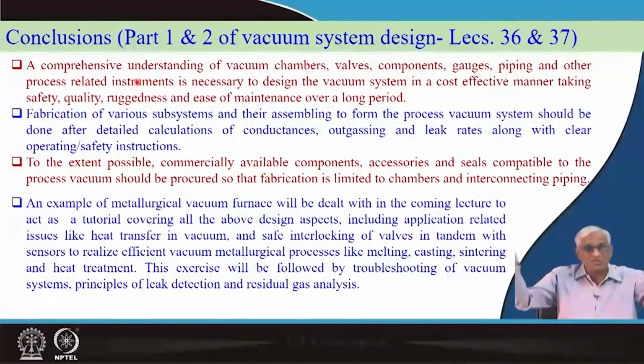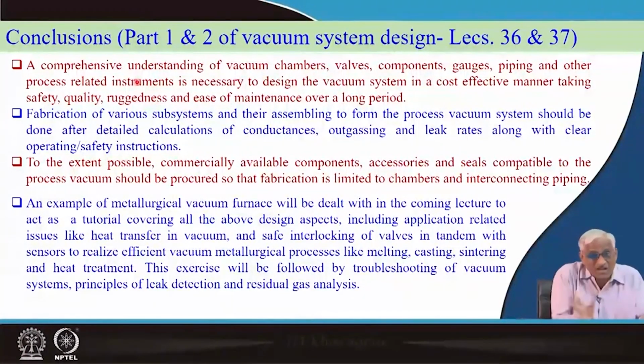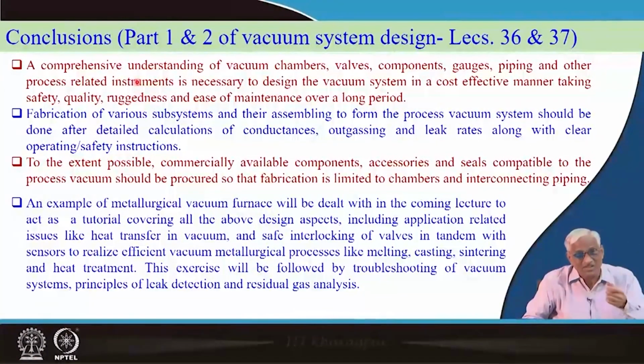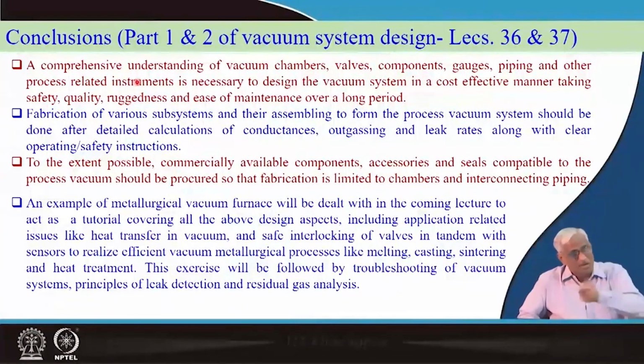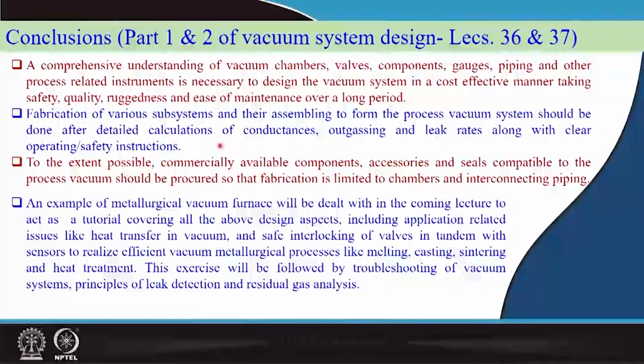A very big space simulation chamber, if there is a sudden problem, it is so big it may even suck your shirt if you are suddenly nearby and you are in a hurry, you are in a worry, you try to close something and you are in trouble. Venting a large system, later we will see in the space simulation. If you make a mistake that you have vented when sound is reduced, you suddenly open the main door, but still you might have vented it to a little over pressure. That over pressure into the door area is so enormous a force, it will hit your face. So, all these aspects the designer has to keep track of.